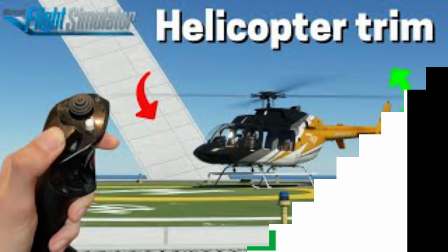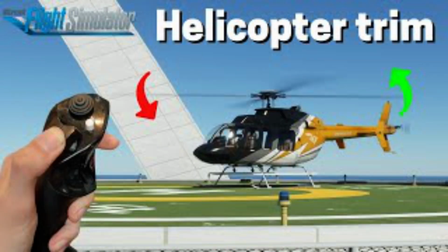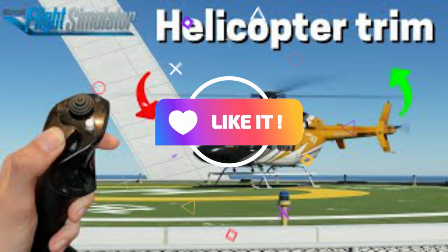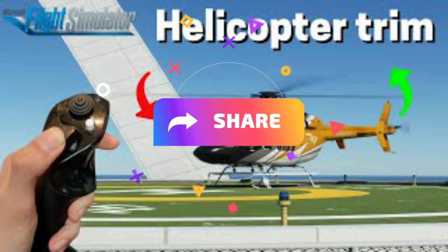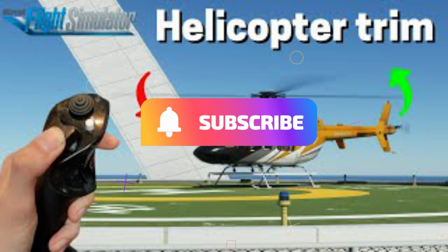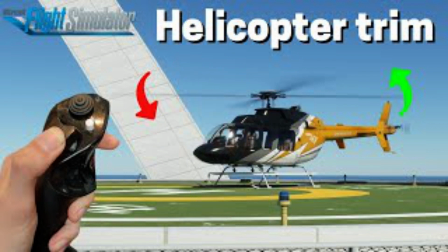Force trim. Force trim was a passive system that simply held the cyclic in a position that gave a control force to transitioning airplane pilots who had become accustomed to such control forces. The system uses a magnetic clutch and springs to hold the cyclic control in the position where it was released. The system does not use sensor-based data to make corrections, but rather is used by the pilot to hold the cyclic in a desired position.